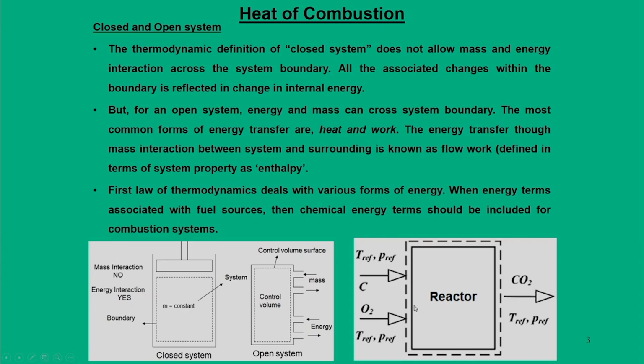Such a system can be viewed as a closed system when you deal with the reactions happening within the reactor. But if you deal with the complete system, involving entry of carbon and oxygen and exit of carbon dioxide, then you can view it as an open system. With this philosophy, heat of combustion, which is normally represented as an energy interaction as heat for a thermodynamic system, is interpreted as heat of combustion. So, here the heat release is interpreted as the heat of combustion.